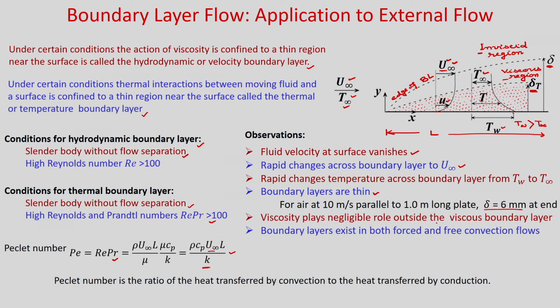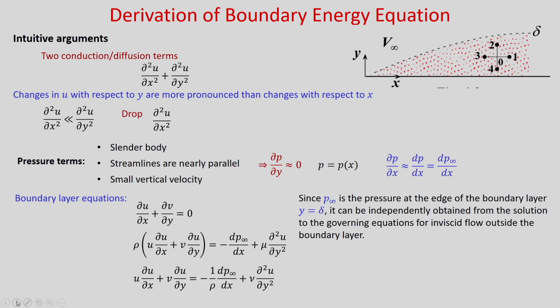Viscosity plays a negligible role outside the viscous boundary layer, which is your inviscid region, and boundary layers exist in both forced and free convection flows. Now, we will use two different approaches to see which term we can drop from the governing equations. First, let us use intuitive arguments.